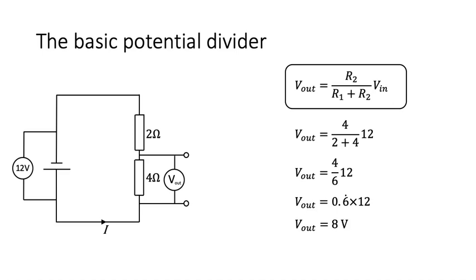So in the last part we just introduced the basic potential divider circuit, which is a great circuit, it's very useful. If you know you're going to have an input voltage of one particular potential difference and you want another one, and if nothing's going to change, if that's just a question of controlling a supply, you don't have maybe much of a choice of what supply you have to be using this, but you know you want a particular output for the rest of your circuit, then you can set up a simple potential divider using the two resistors, no problem. But that's not everything it can do.